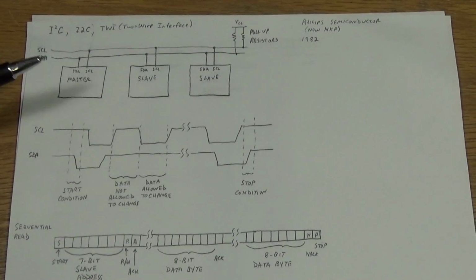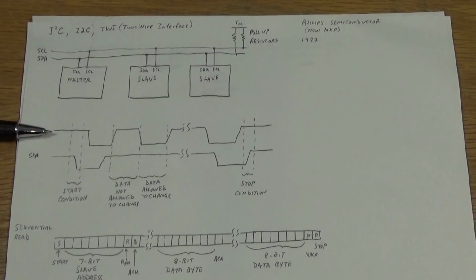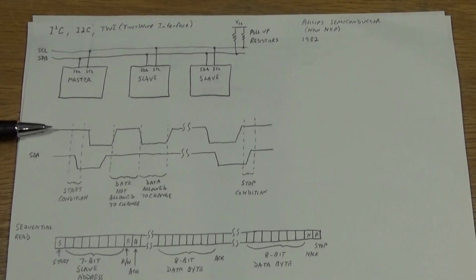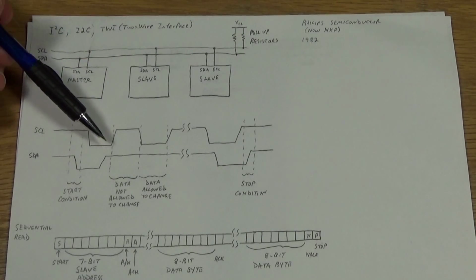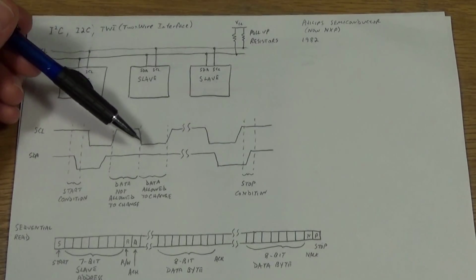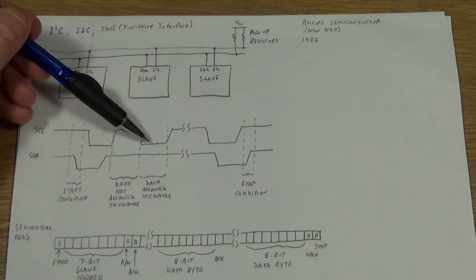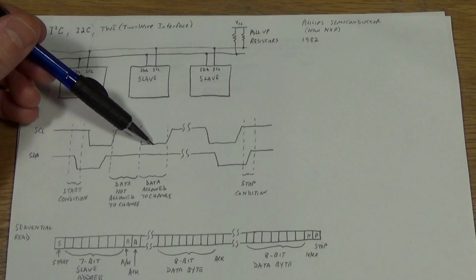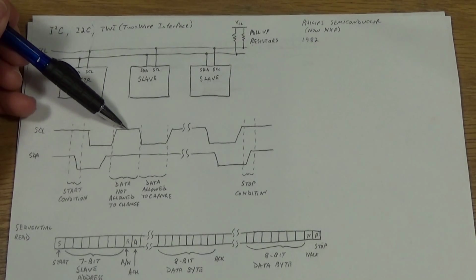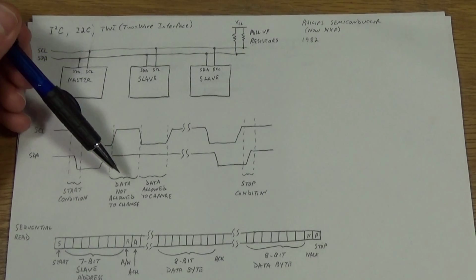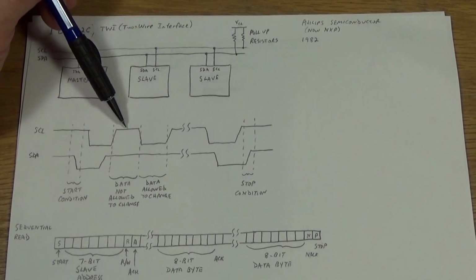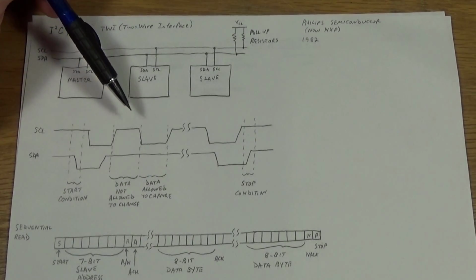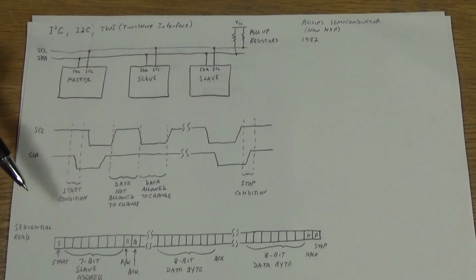So the normal state here, when nobody is active, is the clock and the data lines are held high by the pull-up resistors, and the data is clocked in with the clock line here. The data is allowed to change when the clock is low, but is not allowed to change when the clock is high. Sorry, I got that wrong. Written right in front of me and I mixed it up. And that leads to two different conditions that synchronize communications on the data bus.